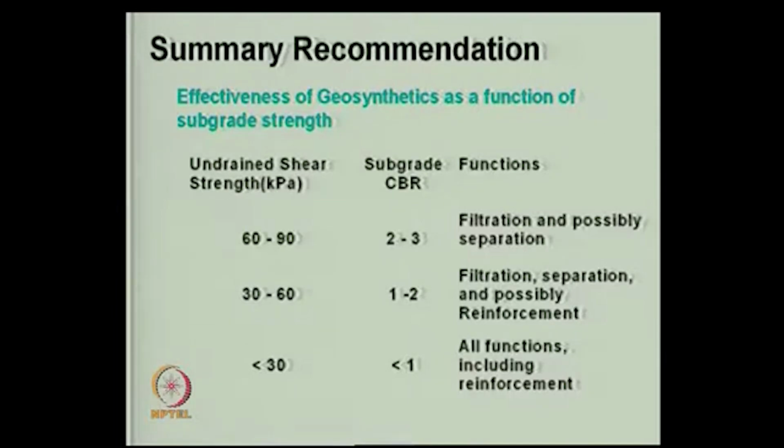Like you can design a pavement based on IRC guidelines or whatever. One can design, depending on 1% CBR, what is the thickness of the crust required, one can calculate. We will show some calculations on these lines in this lecture today.